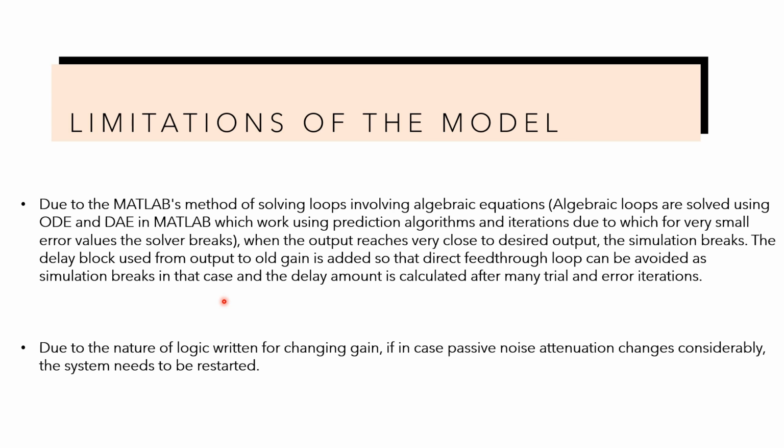Also, as you had seen in the delay block, the delay there was given as 4 samples, which we had found after trial and error works the best. The next limitation of our system I want to point out is that the nature of the logic which we have written is that the gain constantly increases. And if due to some reasons the passive noise attenuation of the system changes, then our system cannot react to it properly. It needs to be restarted.